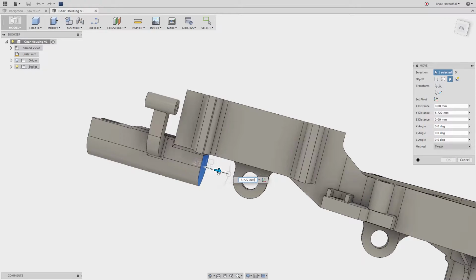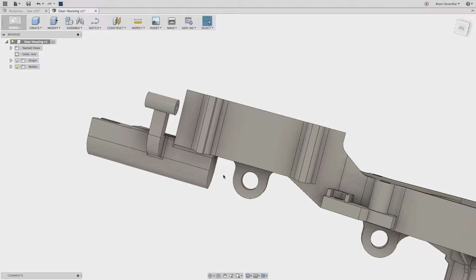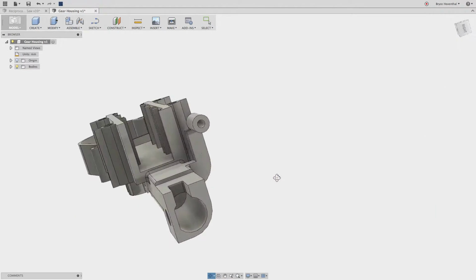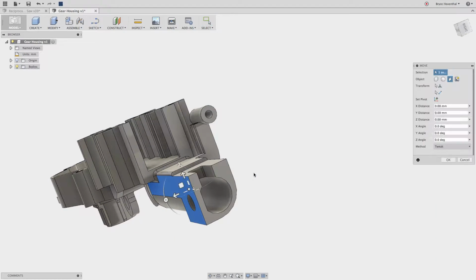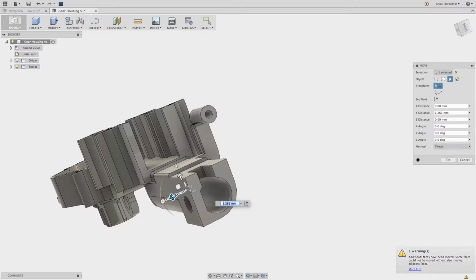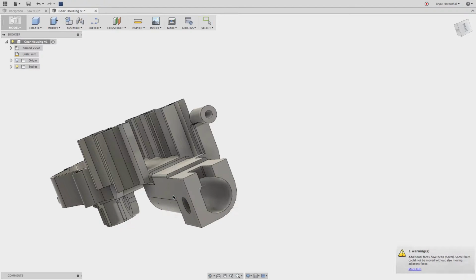Fusion 360 has direct modeling tools to aid in making changes to dumb geometry. We can increase the length of this frontal portion and the width by simply selecting the face and dragging it. Fusion 360 will heal the fillets and curves to the correct location.